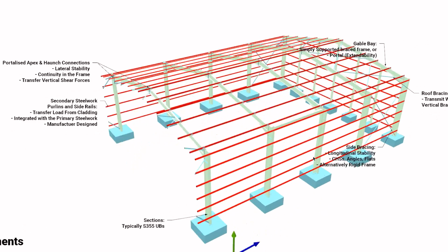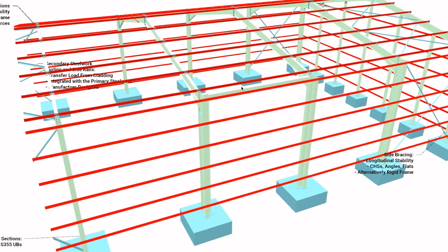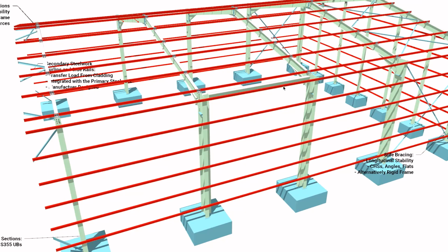And if I can zoom in to show that here, hopefully you can see that. But we need to make a note to check deflections on our portalized bay if we're using these, as they're less rigid than a brace bay.